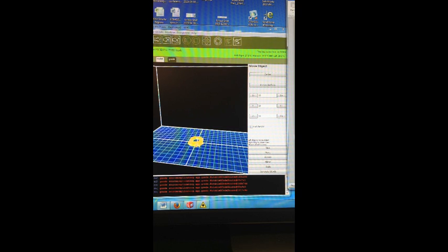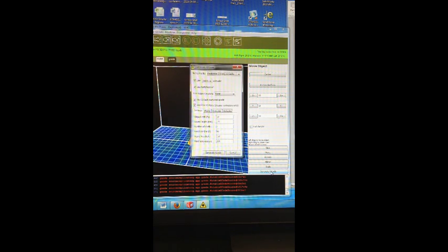After positioning the object, you will want to generate the G-code. Go to the bottom right hand toolbar and select Generate G-code. The window pops up. Directions for generating the G-code can be found in the printer guide. For our example, we are using the material ABS. The slicing profile default for ABS is replicator slicing.